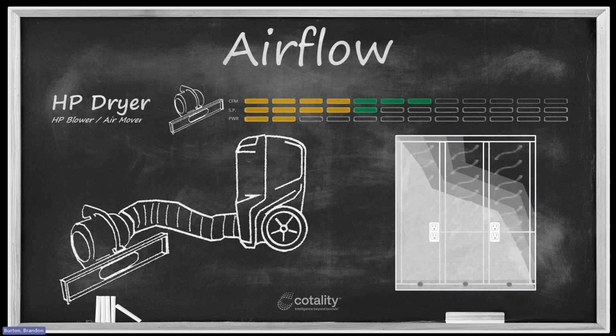Now, with all of that said, I would not use an inter-air drying system on this cavity unless I have data that shows me that the surfaces are wet inside the cavity, right? And this is the reason why we don't use inter-air drying systems automatically when we have a wet wall. We've got to think logically, where did the water come from? How did this wall come to be wet?